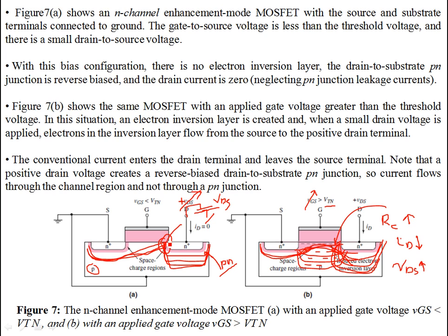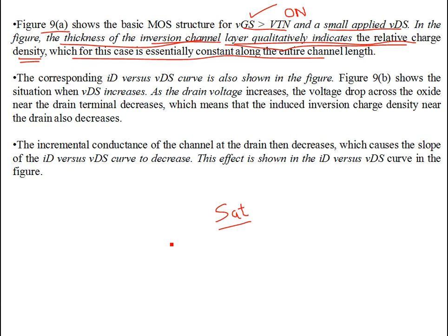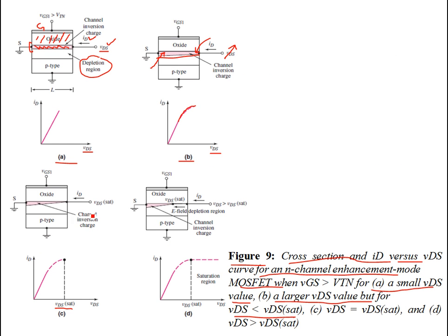The width is zero at the drain side. You can see this over here. This is your source, this is your gate, that's your substrate, p-type substrate, grounded body. So at your drain the channel width is zero over here. There are no charge carriers.